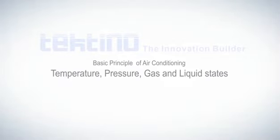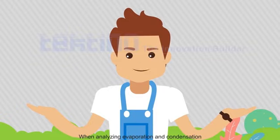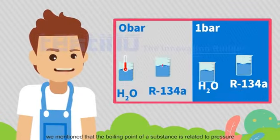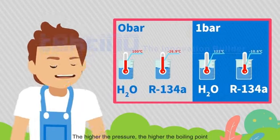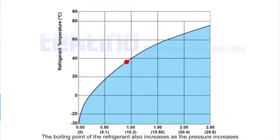Basic principle of air conditioning: temperature, pressure, gas and liquid states. When analyzing evaporation and condensation, we mention that the boiling point of a substance is related to pressure. The higher the pressure, the higher the boiling point. The boiling point of the refrigerant also increases as the pressure increases.